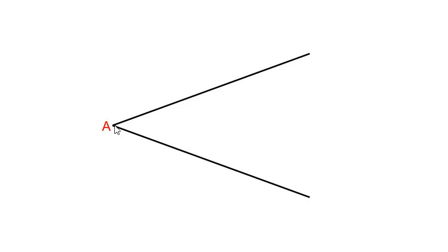Okay? And what we're going to do now is placing the needle of the compass on this point here of the vertex, we are going to draw a circle which will intersect the two arms of our angle. You can draw it any radius you so wish, but make sure you draw it large enough so that you leave room for more construction lines. So we'll just draw that circle now.